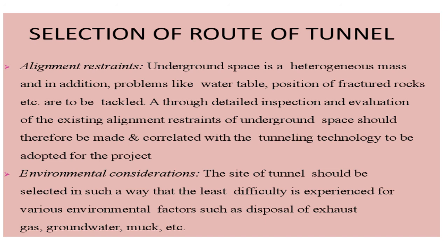So if you are cutting the soil, a suitable region should be there where you can fill the soil. If you can find a region where you can go and fill it, then it will be more helpful. So all these things have to be identified properly when you are going for the routing of a tunnel.